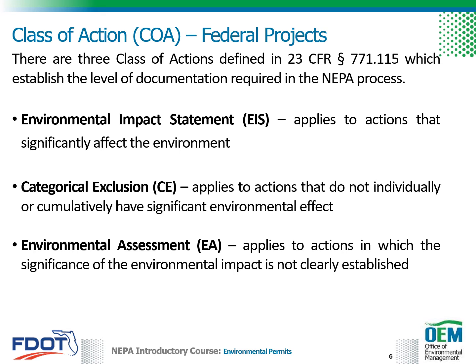There are 3 federal class of actions defined in 23 CFR Section 771.115, which establish the level of documentation required in the NEPA process. The first is an Environmental Impact Statement, or EIS, which applies to actions that significantly affect the environment. The second is a Categorical Exclusion, or CE. This class of action applies to actions that do not individually or cumulatively have a significant environmental effect.